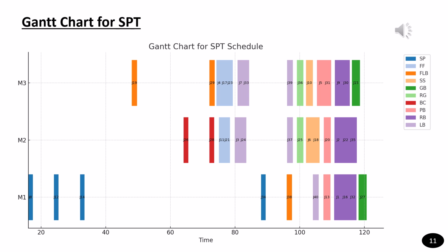This chart shows the job allocation when we use the shortest processing time strategy. While SPT is useful in many classical scheduling problems, notice some inefficiencies here. Jobs are bunched based on processing time without considering mold changeovers or job release shifts. As a result, we can see idle times, long setup transitions, and sometimes jobs starting late even though machines were free earlier. This demonstrates that SPT fails to account for the real-world constraints of injection molding operations.